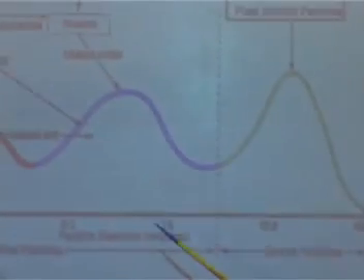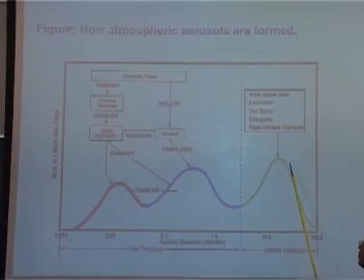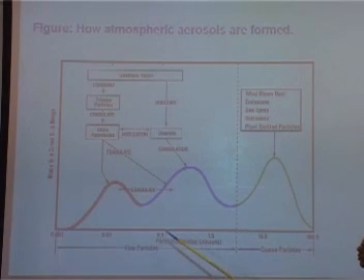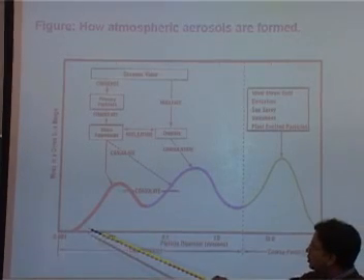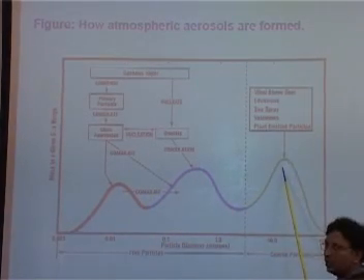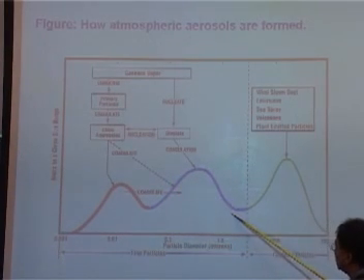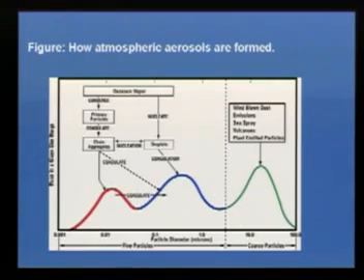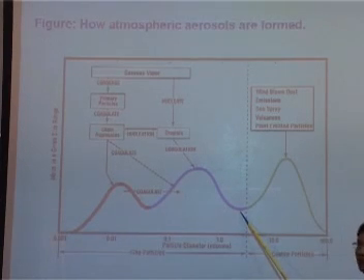See, what will happen, these particles can coagulate, but these particles don't coagulate. Whatever distribution you get, they are there. So what will happen as you move a little away from the source? This trimodal distribution, as you see, eventually becomes something like this. Therefore, in all our studies in air pollution, we are generally dealing with the fine mode, that is up to something close to 2.5.